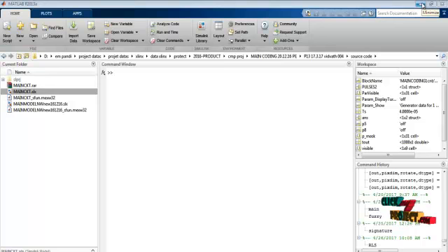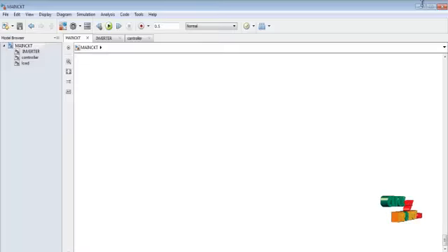Next we see the running process of our product. This proposed implementation is done in the MATLAB simulation environment. First, open the MATLAB main window. After that, we create a new model file. After opening the new model file, we assign the name and check the solver conditions. After that, we open the Simulink library browser. From the library browser we mainly use two toolboxes: one is SimPowerSystems, and the other is the commonly used blocks.